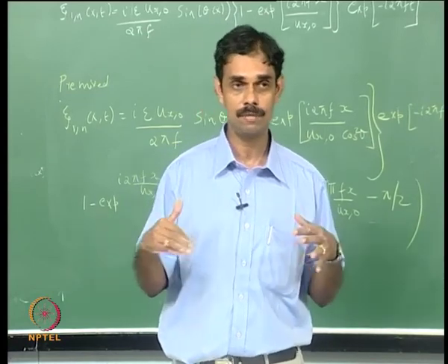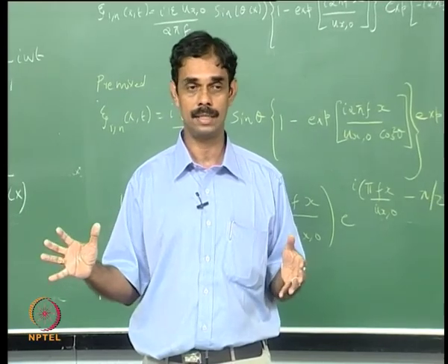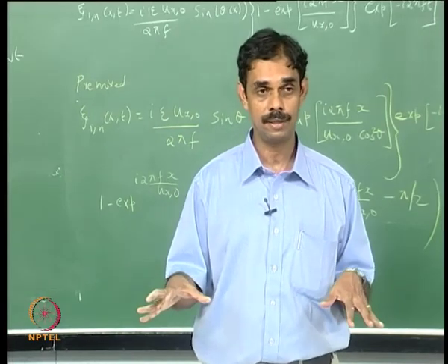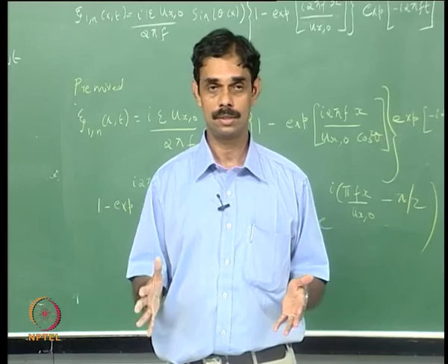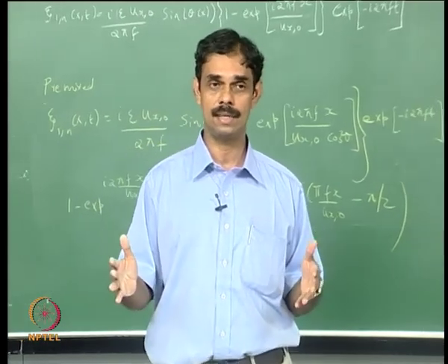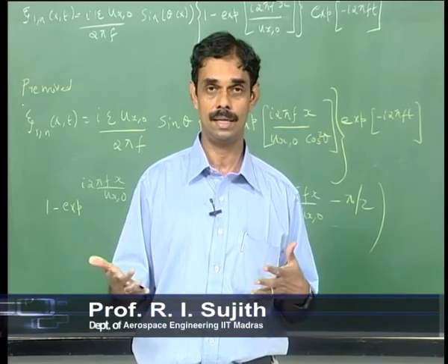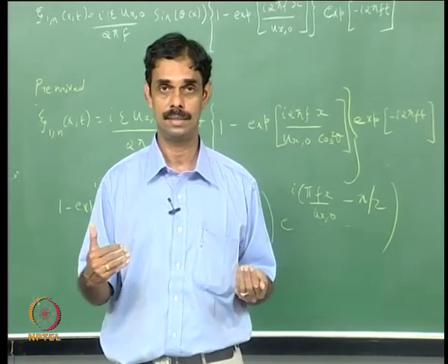So for each situation you can construct a model for the unsteady heat release rate, and then you plug it into the corresponding wave equation, and then you solve in whichever way you are solving. So I hope you will be able to extend all this analysis to your thermoacoustic system and be able to analyze what happens to it, both the linear stability and the nonlinear stability analysis. Thank you.